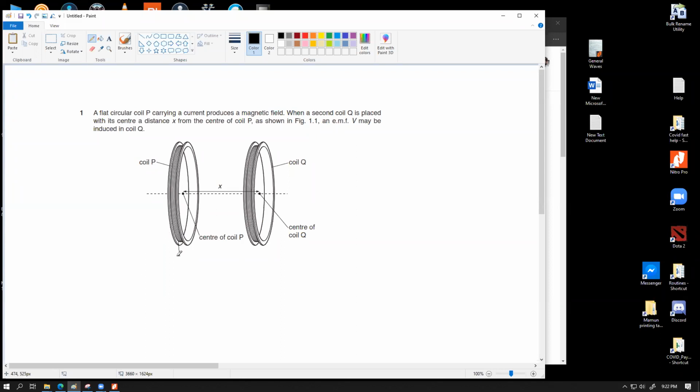So this coil should be run with an AC supply, with a switch, with an ammeter, with a variable resistor, just for the sake of controlling the behavior. And it goes on over here. And to observe its voltage, we can also connect a voltmeter across the coil, not across the source, across the coil. So on the two sides of the coil.